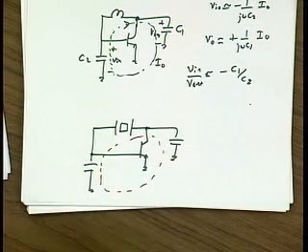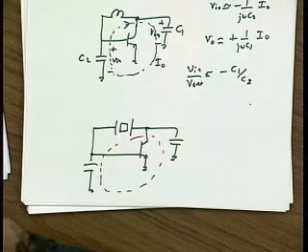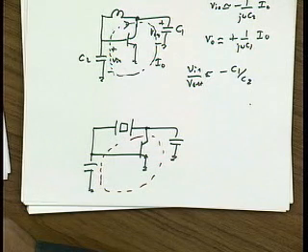A question? Yes. So far we always have assumed that the Q of the inductor dictates the overall Q because it's much lower than the Q of the capacitors. But now, since we have such a high Q inductance, what about the Q of the capacitors? That's an excellent point. Yeah, when you're talking about a Q of 1,000,000, you have to include all the loading effects that will occur.